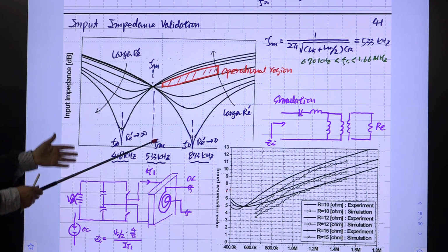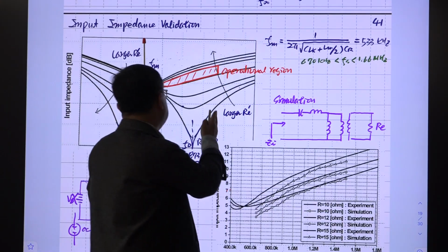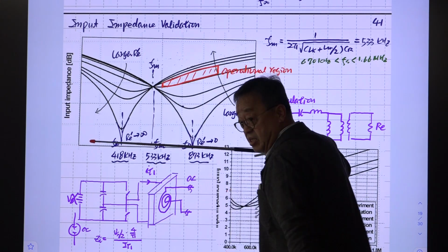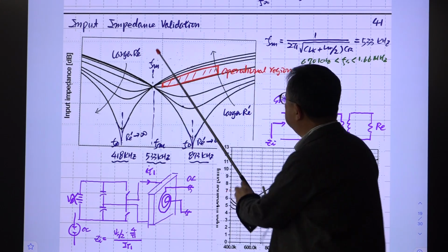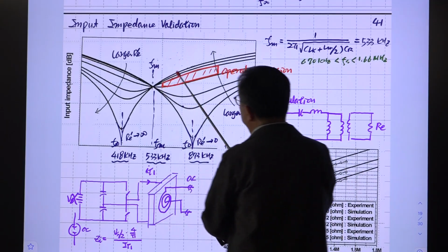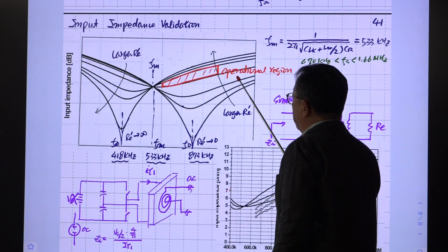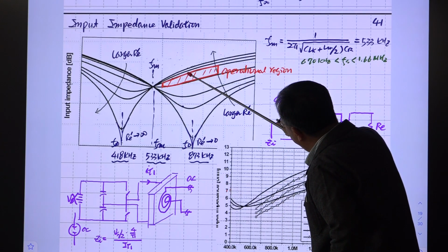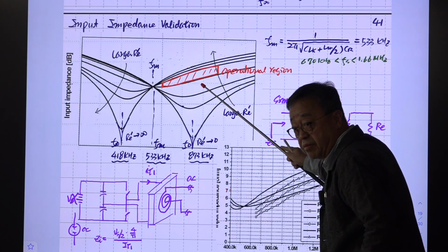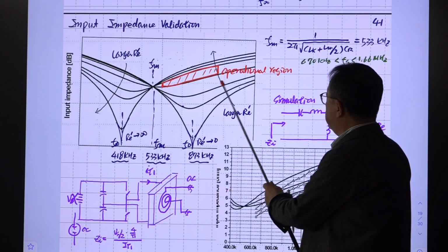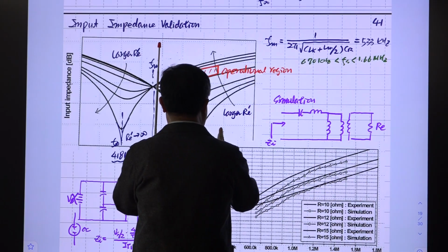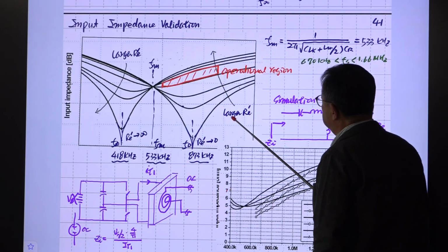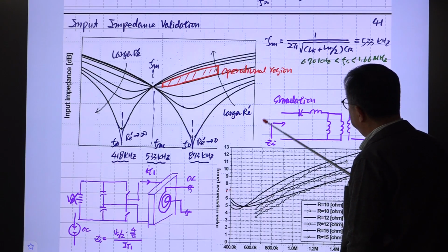This is possible because we know the range of switching frequency here. So always this axis is frequency. With that information, I can specify this like this. This is the operational region for our converter. So this region might be okay, but this region is bad because the switching frequency is changing widely like this, right?